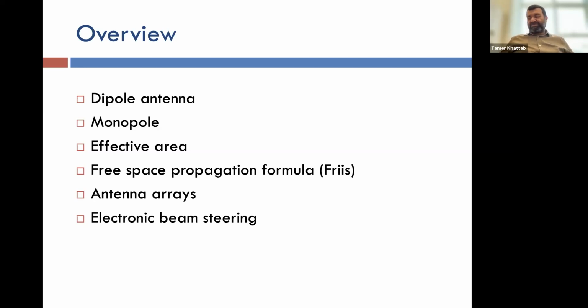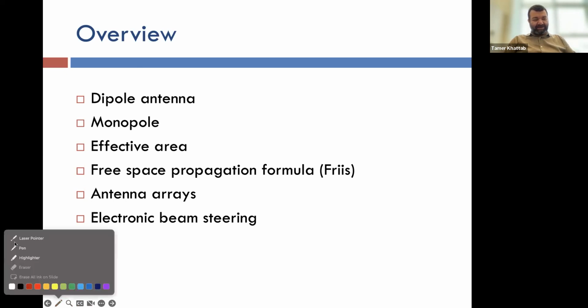We started with a theoretical antenna called the Hertzian dipole, a very short dipole antenna. Very short here means that the length of that antenna is much smaller than the wavelength of the signal. It's easier to analyze this small one, and then we use it to figure out the analysis for a more practical, dimension-wise antenna. So regardless of the details of the analysis, we found that the electric field is typically, if you are dealing with spherical coordinates centered at the center of the antenna,